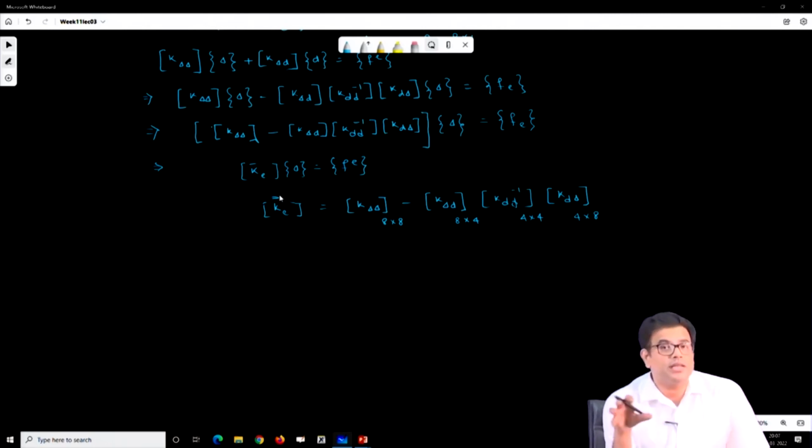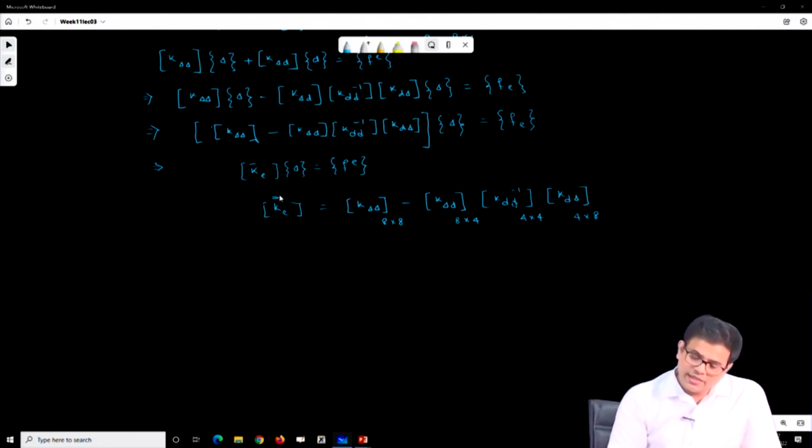The patch test we discussed briefly in the previous class is the completeness criteria. So if I apply a linear polynomial displacement on the boundary of a standard patch of Q4 elements, I should recover the exact results at the internal nodes. So it passes the patch test only if the element is rectangular.